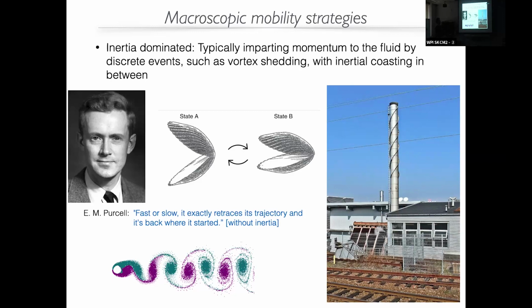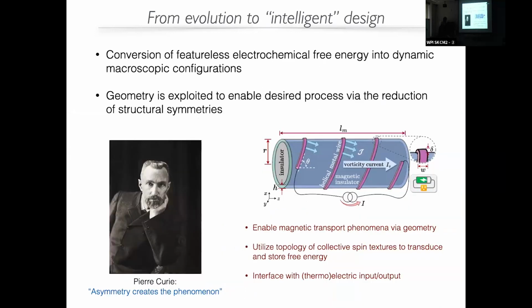So this little spiral here is designed to streamline the airflow and minimize vortex shedding, to prevent the possibility for the stack to start resonating with the physics of the vortex shedding. Anyways, this is just some fun facts. You can look it up on Wikipedia, but you'll see these facts also manifesting in our story from a completely different perspective.